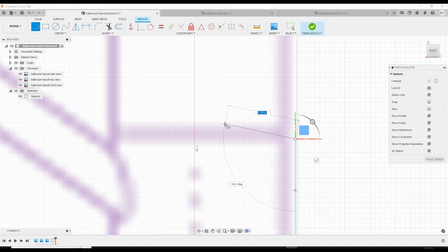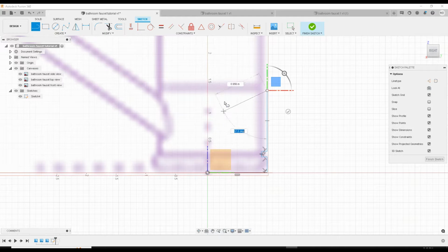And now we're going to carry over, and you see it kind of locks into the 90-degree constraint, right? So it's going to, oh, here we go. What we need to do, let's kind of hover back down to the origin, drag it back up, and you see it snaps to the origin. So if you drag it up, it actually snaps along this line, and it would automatically create a 90-degree for you. So you click it, and it's going to allow you to click onto the next.